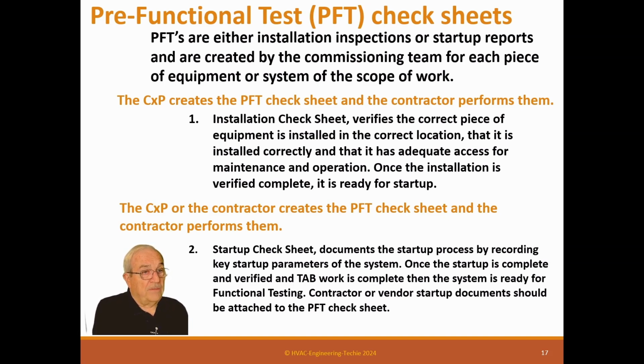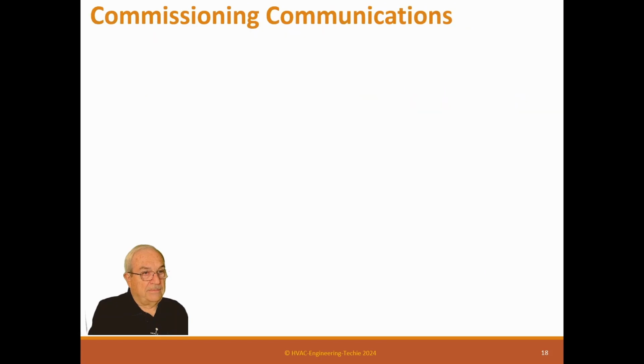Now, the startup tests have something in them that's important, and that's actual data. They take all the electrical data, all the set point data, all the mechanical data, and it's actually in that form. So you'll have volts, amps, set point data, pressure data, all that kind of stuff actually in there so that everyone can see what it looked like when it was brand new. It's really important. So, 10 years from now, the owner's having a little issue. You can go back and look at this report and say, this is what this machine looked like when it was brand new. So now we can see what it is today.